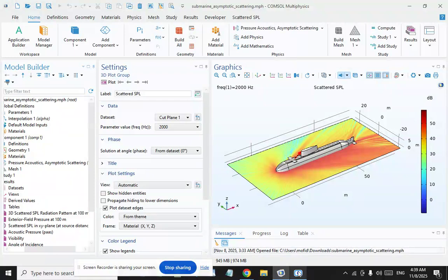When the simulation is run, the ocean attenuation material stands in for the inherent losses associated with the transmission medium. Because its parameters are obtained from a large amount of experimental data, this attenuation model can be considered semi-analytical in nature. There are other parameters that contribute, such as depth, temperature, salinity, and pH.